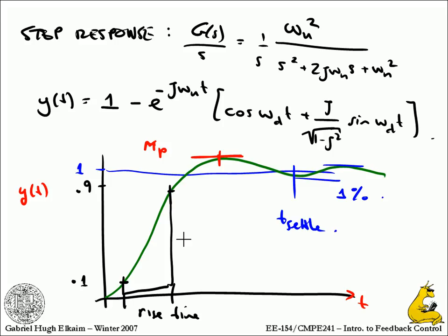I want it to be sort of pointing at that star in 6 seconds, and because my optics need to be stable before I can actually take an image, let's have a settling time of about, I want it to be within 1% of the final after about 30 seconds. So I want it to get really close so I can start sighting it and stop wobbling by about 30 seconds, and I don't want it to go past more than, say, 12% past where I'm aiming for. So all of a sudden, you can now take those specs, which are in the time domain, and relate them back to where it should be within the complex plane.